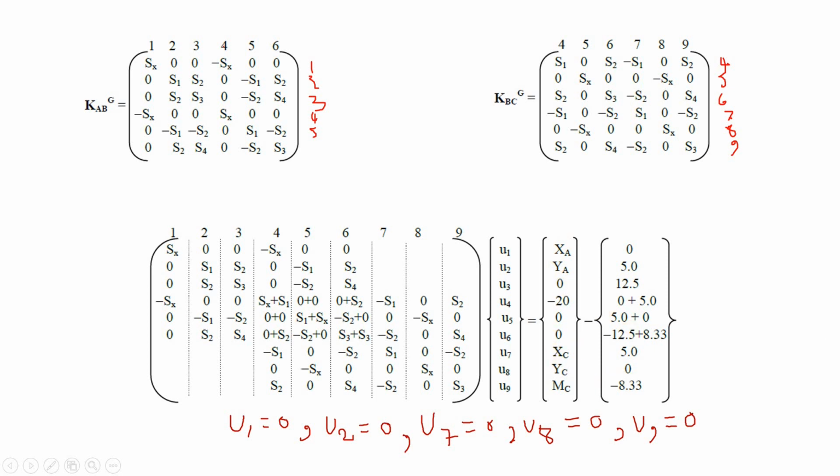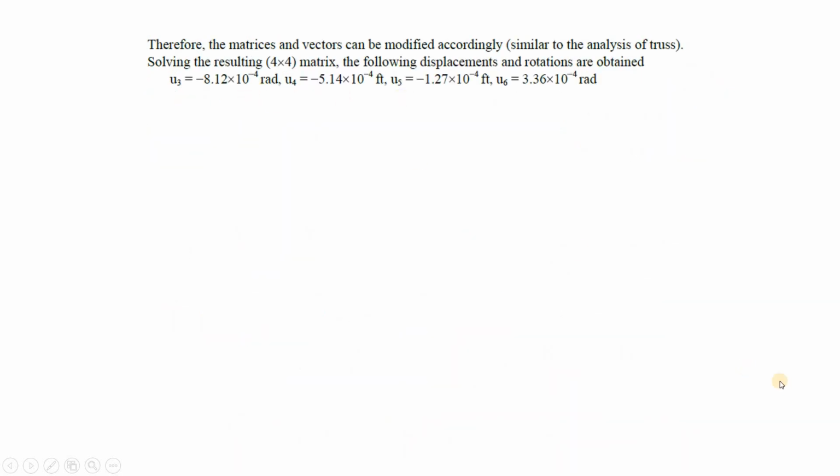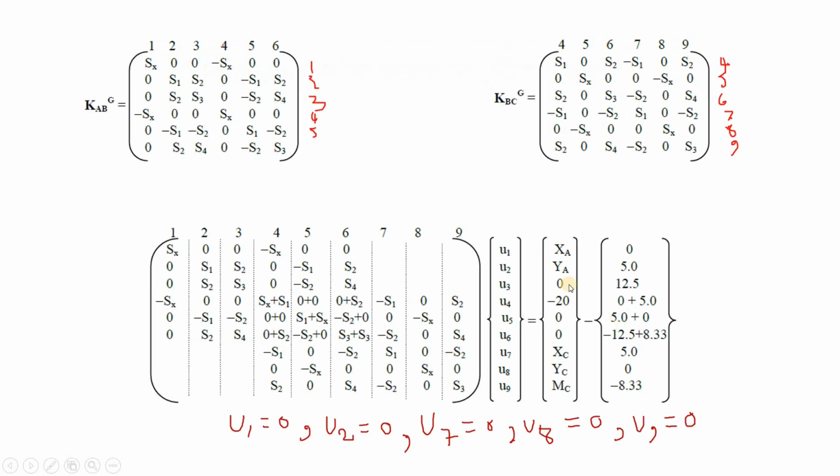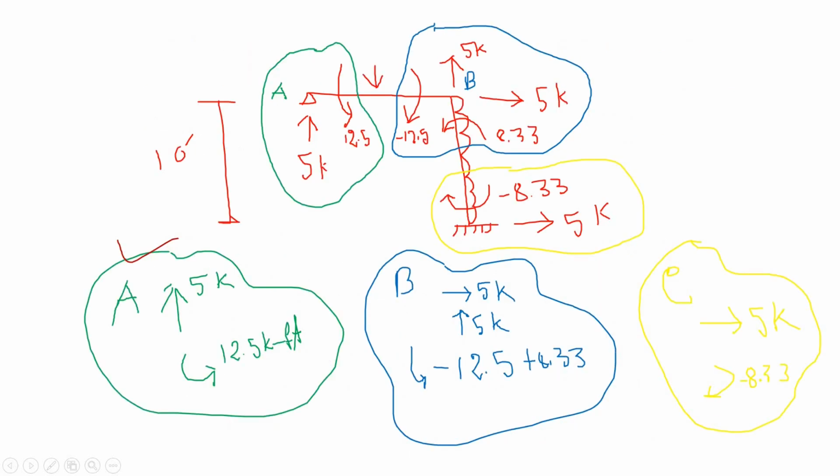I mean, once you get all of the deflections, you can easily get the reaction forces from here. And once you get the reaction forces, you can easily calculate the shear force and the bending moment, right? You can even do the shear force and bending moment diagrams as well. Okay, but what if we just wanted to find out the deflections, right? What if we just wanted to find out the deflection?